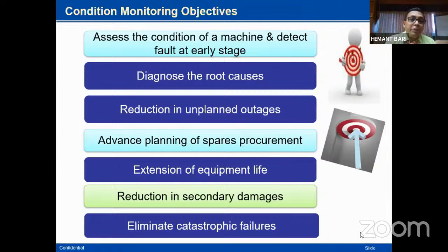Sir, इसका वाइब्रेशन 2.5 चल रहा था, अभी 6.5 हो गया है, and it shows a misalignment in the machine. Immediately all resources will help you. Sir, इसका acceleration value 2.1 था, अभी 4.6 हो गया है, indicates a bearing damage. You are allowed to replace the bearing.